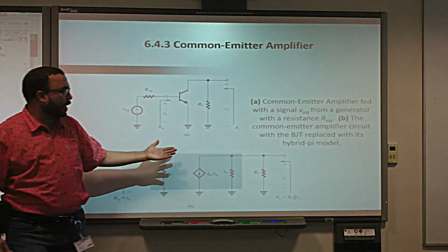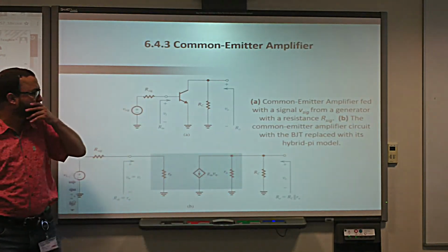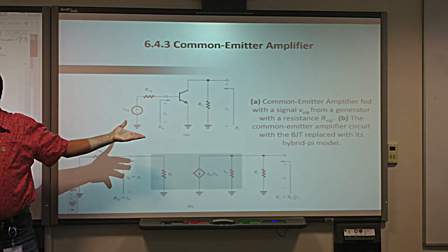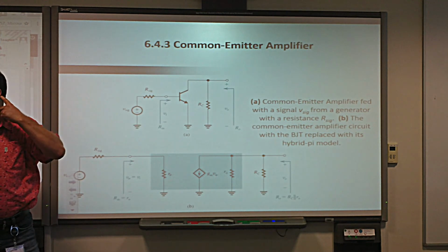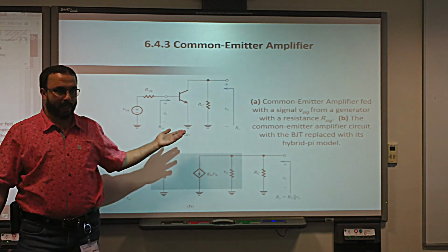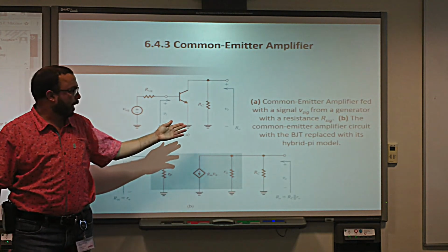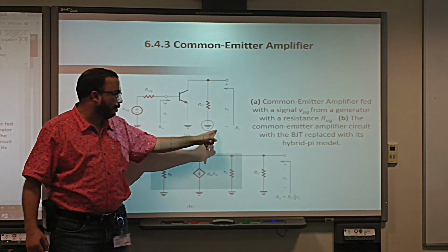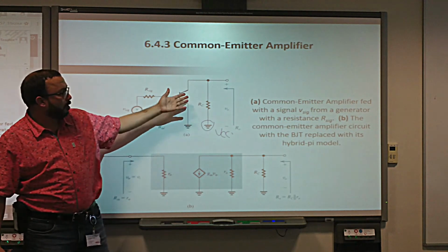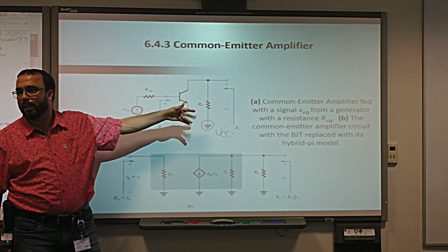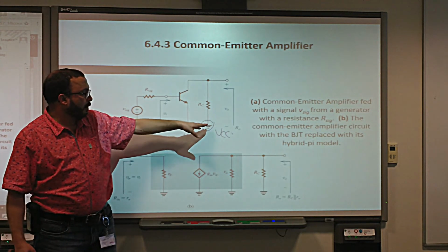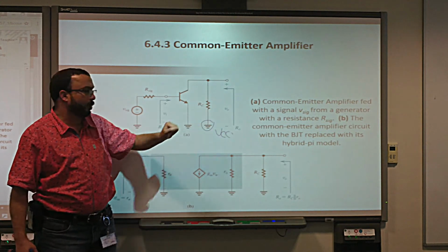We start with the first amplifier, which is the common-emitter. As you can see here, this circuit, is it in DC or AC? What's the first stage we need to study the amplifier? AC. So we have to make our circuit in the AC domain, and it is now in the AC domain, yes or no? Yes, because simply this was actually VCC or VDD if you want, okay? Because it cannot make any current in here, yes or no? Because this is grounded. This is in AC, and in AC, any constant voltage becomes grounded.